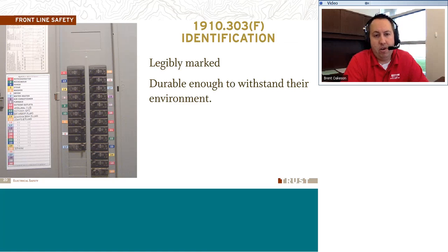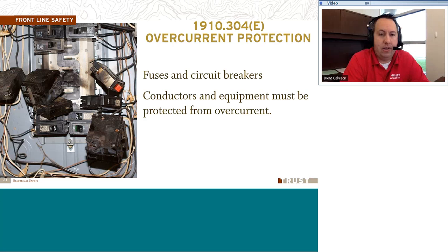It's important to know what your breakers go to. Here's an example. One time I was working on an outlet below a sink I was changing out, and I knew that I needed to shut the power down because I was going to be opening up the outlet and rewiring things. So I went out to the panel and I found the breaker, and it said kitchen, and I turned it off. I go back in to start doing my job, and guess what happened? I got a shock from that. I was lucky enough it wasn't severe. It didn't cause any real problems, but it certainly could have. What happened is I obviously didn't turn off the right breaker. So it's really important to have things labeled. It's always important to make sure and double check that things are turned off and locked out before you go working on things. So the identification is great, and that's definitely a good thing there.